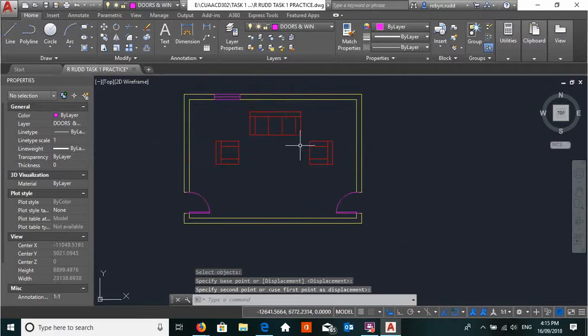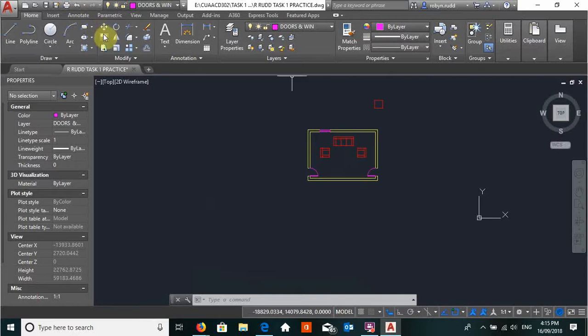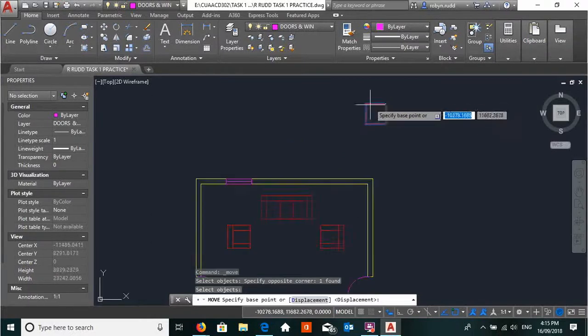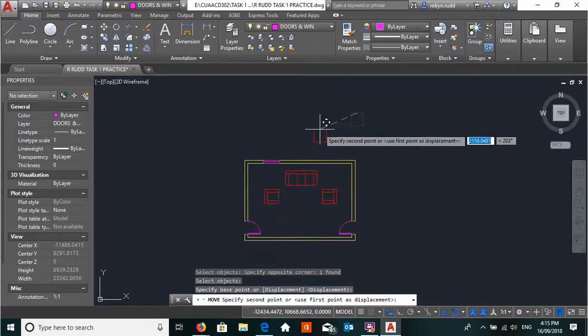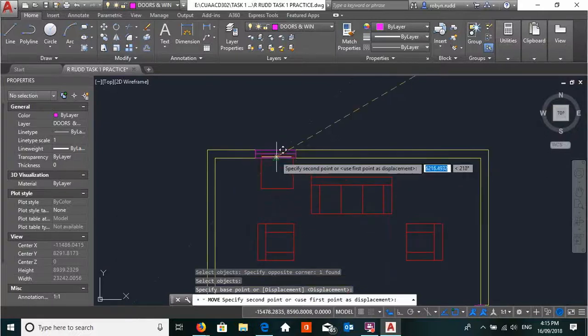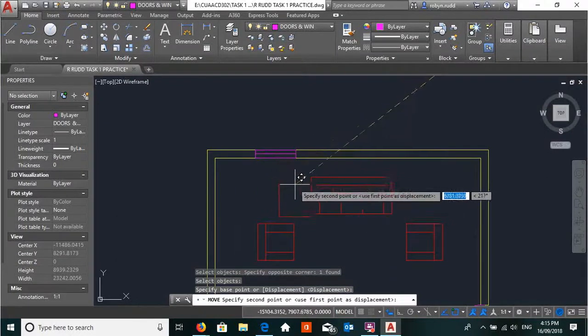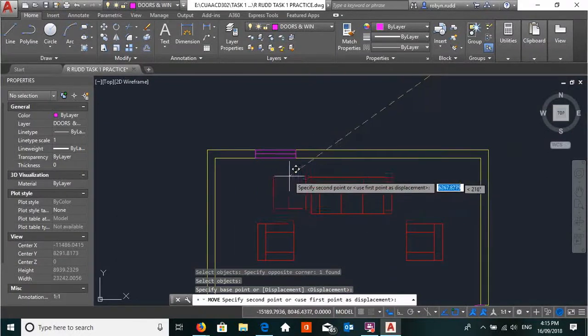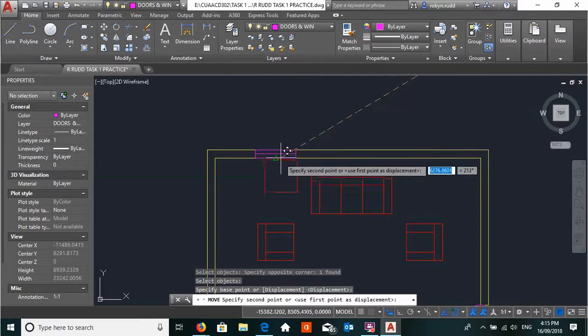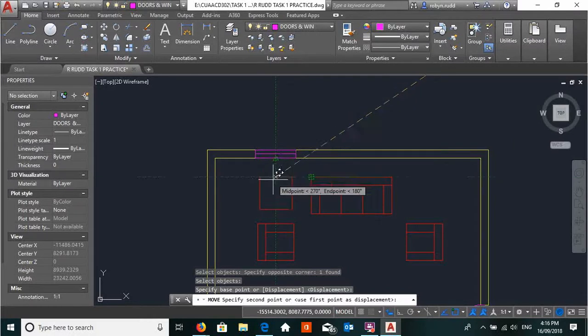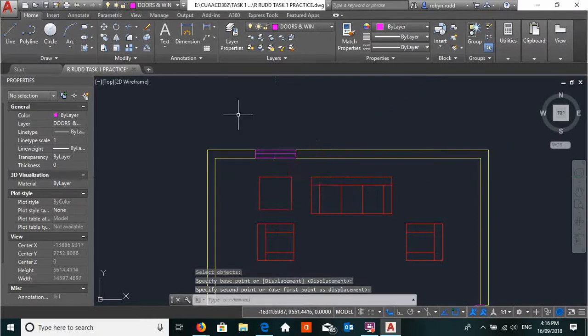And now we have our 3-seater sofa with 2 single chairs, and let's do 2 coffee tables. So let's move this one, selection box, top corner, bottom left corner, click, enter. Where we're going to move it, let's use the midpoint there, and let's get it in the midpoint of the window down here and there, midpoint, so that it all fits in line.